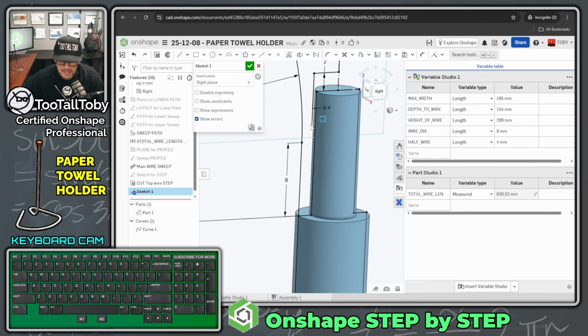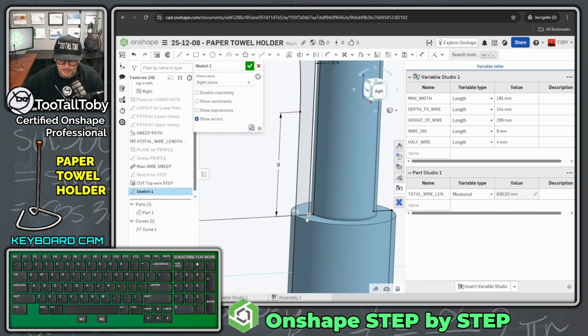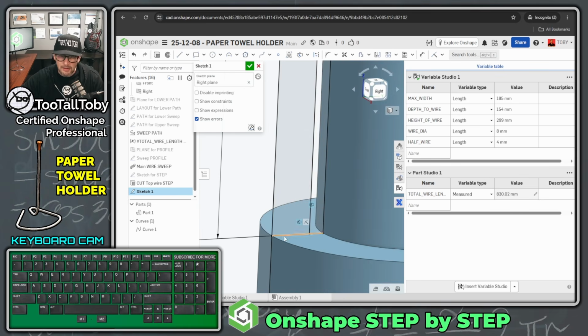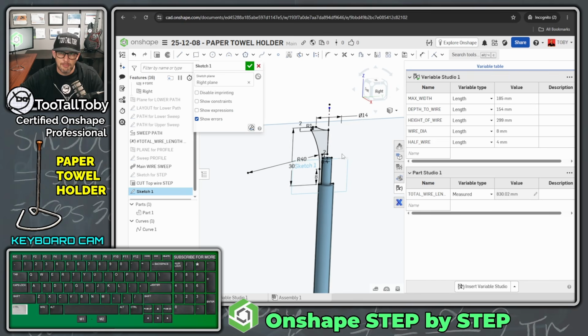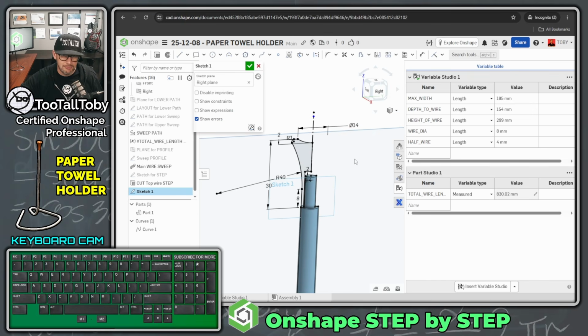And then we can hit escape, and then this point's just going to come all the way down to this other line that we used the intersect for. So that intersect command is super, super helpful in Onshape, and it really helps you when you're designing two parts that are meant to function together, that are meant to fit together. Use that intersect command a lot. I use it all the time.